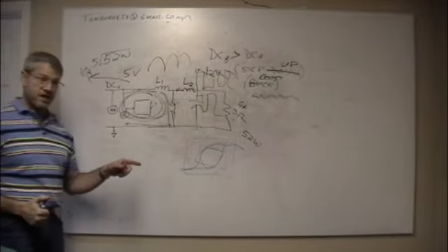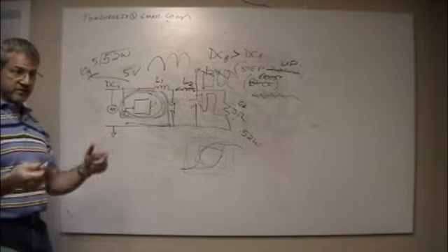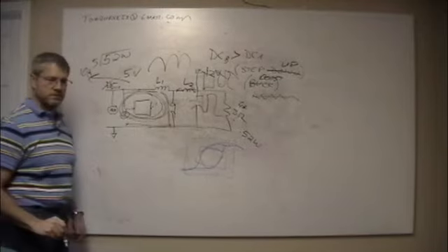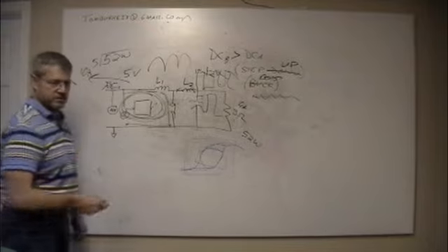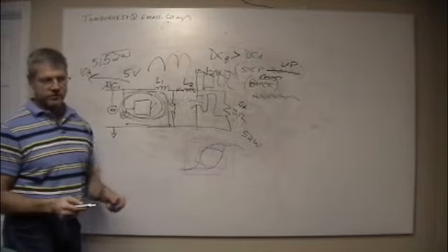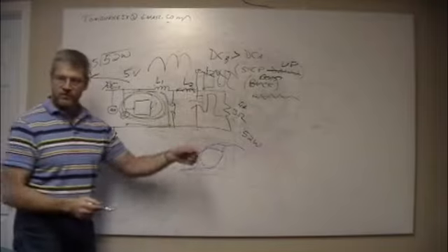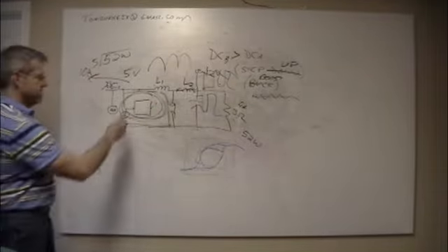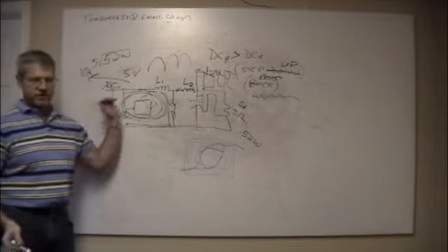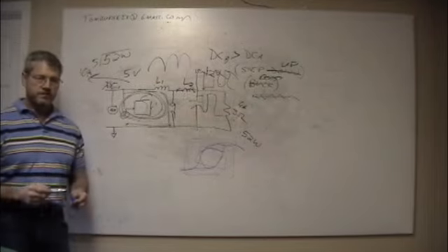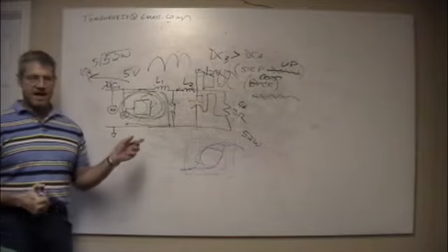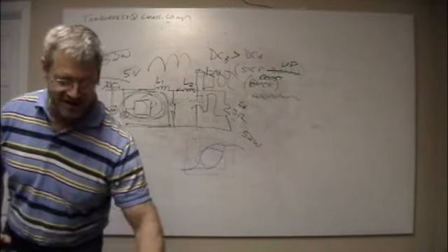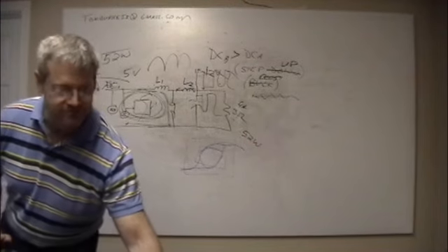Now you can do the same thing with AC. Some of your fancy power supplies these days, this is AC straight off the wall, and now it's all buck converters, right? Because you don't need to go more than 120 volts usually. Usually you want 12 volts and 10 volts and whatever. So this becomes the buck topology. And you might put a transformer there to isolate the two so you don't have AC going straight into your circuit, because if something bad happens, it's really bad. It doesn't just go bad, it goes really bad. You're not replacing a few things.